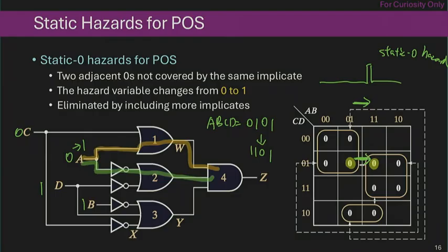Because it's inverted, when I change this to a 1, this one will become 1 first to set the output to a 1 before this one comes down to 0. So the top path will go from 0 to 1 first before the bottom path takes a longer period of time to give you a 0. Momentarily, while the first one is a 1 and the middle one is still a 1, the output momentarily becomes a 1.